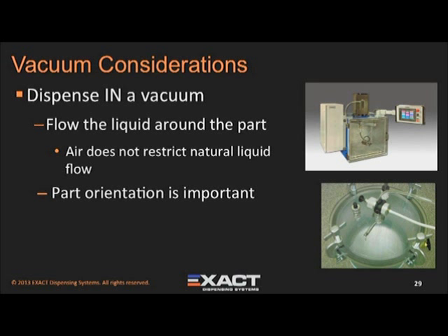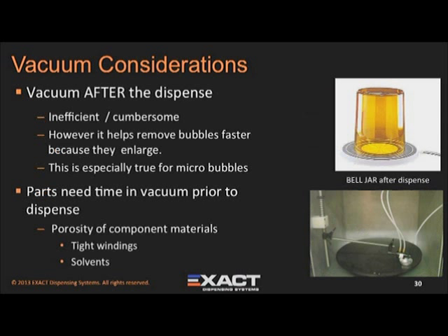There are times when you should dispense in a vacuum. By dispensing in a vacuum, the liquid quickly and easily flows around the part as there is no air to stop its flow. There are a lot of dispense in vacuum equipment options available, and you can see some of those on the slide in front of you.